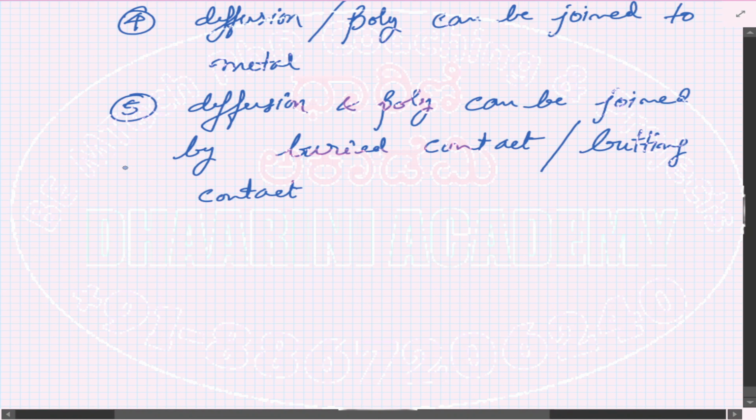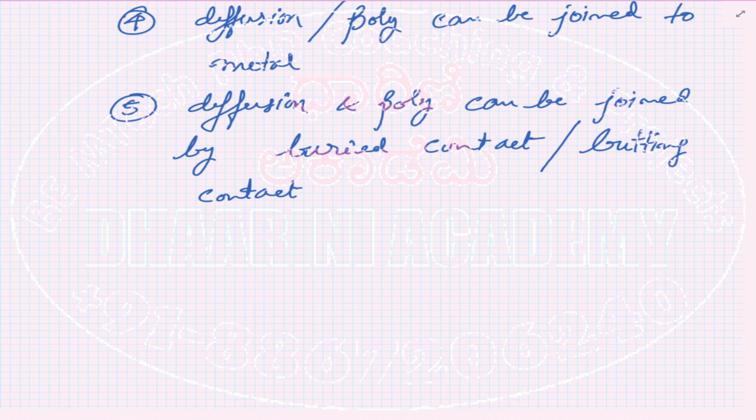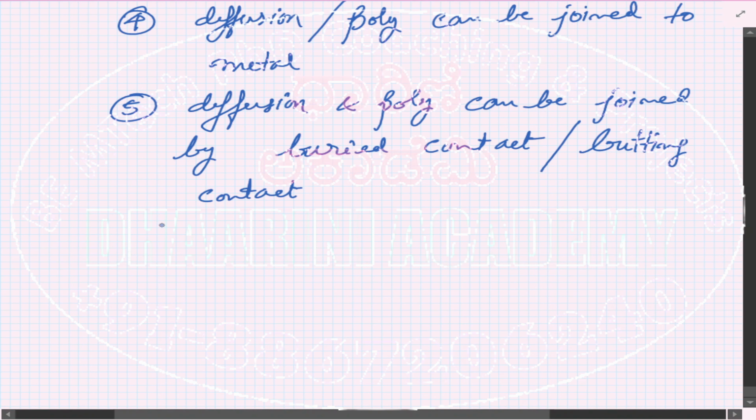Okay, if a second metal layer is available using a double metal process, whenever two metals cross, there can be a possibility of a contact, so you should be very careful over there. Two metal layers can be joined. If you want to join, you have to use what is called a via, VIA.